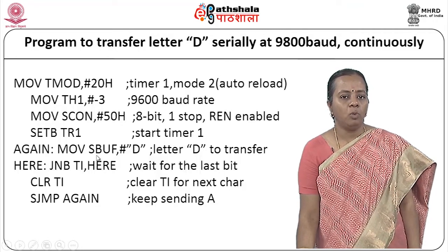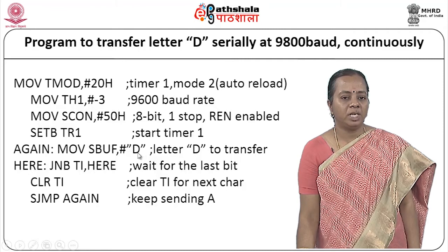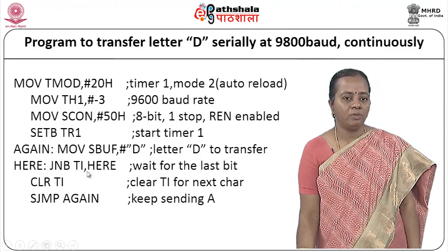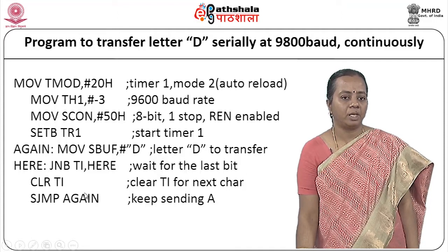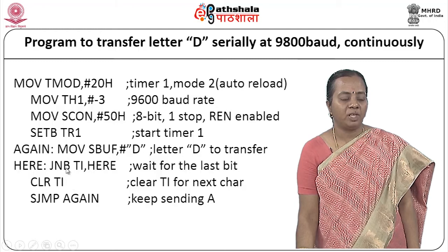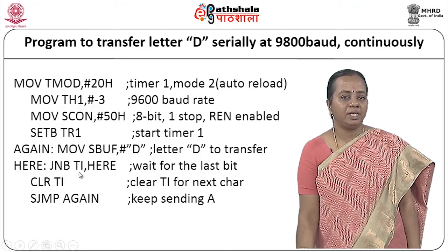Now MOV SBUF, #'D'. So the D is moved to your SBUF. The data is available in your SBUF, and now it is transmitted outside. We will be watching whether TI is equal to 1.